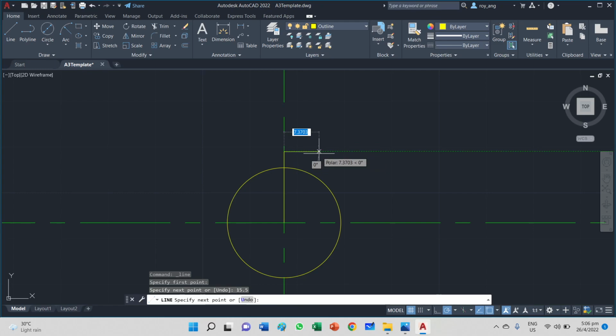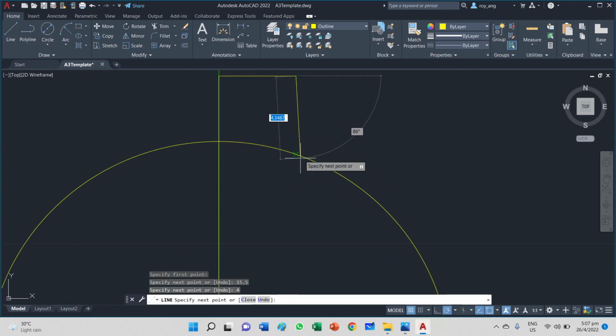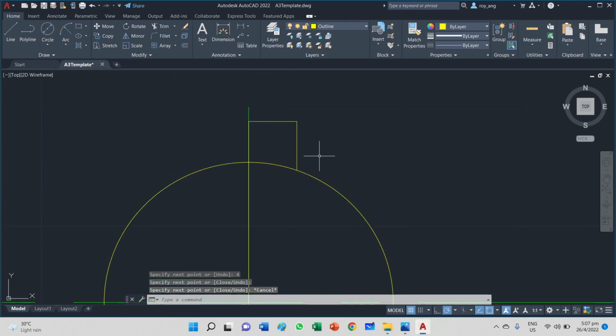Now the width of the keyway: if you look at the top of the drawing, there are two numbers, one is 10 and one is 8. The width of the keyway is 8, so on one side of it will be 4 millimeters. Then I'll be going down and intersecting this line. Once that is done, I will use the mirror command to select these two objects, right click to accept, then select the two lines, press enter, and I would have mirrored the keyway.